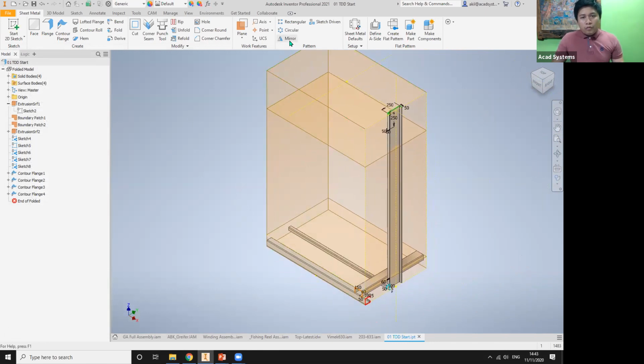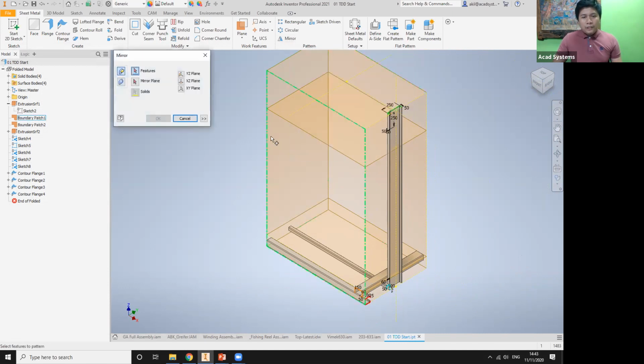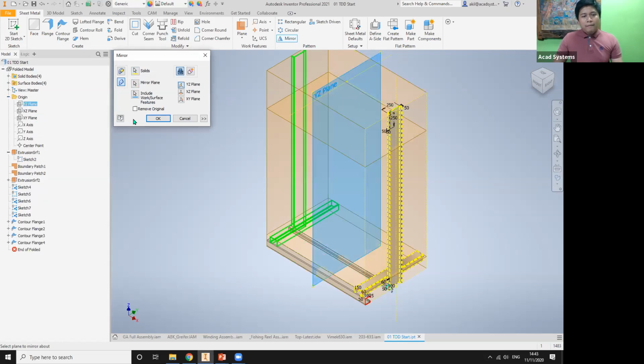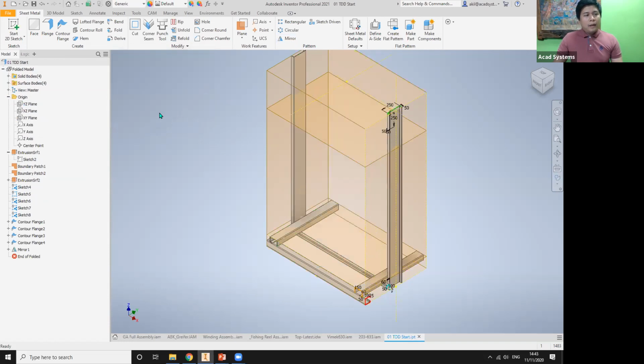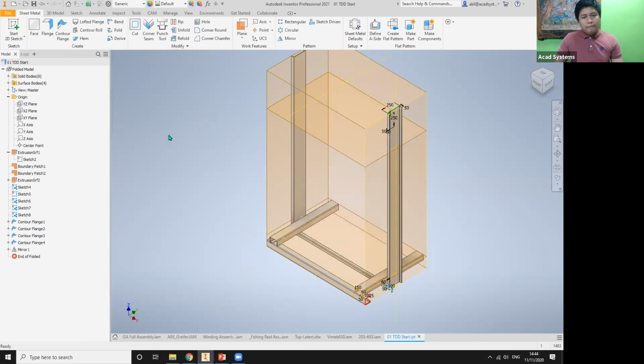So after you're done with the first step, you can do the second step, which is to mirror all the objects by creating this mirror solid. So I create a new solid here. The new solid also, and the mirror plane will go to the origin, for this case, YZ plane. But the problem is with this mirror, I want to make it a new solid. So I need to click on this button, new solid.